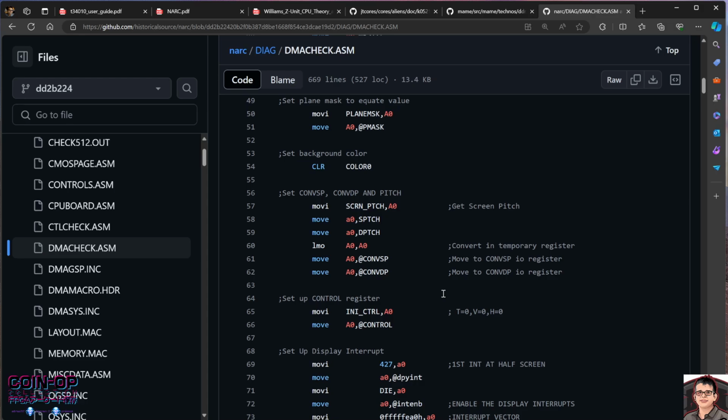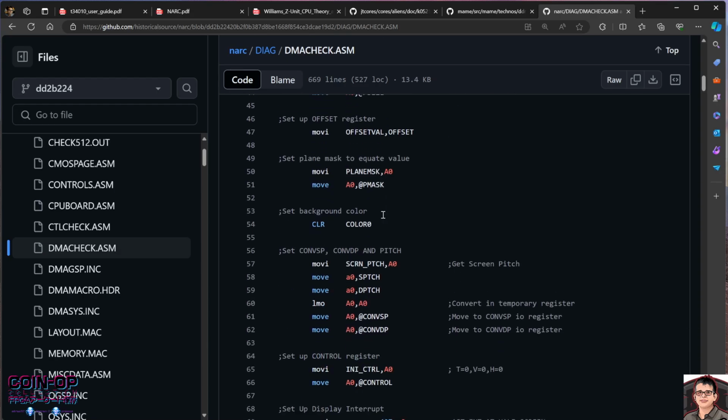I wanted to figure out what was going on, and this is where the source becomes very important. Since there are no hardware sprites, there's no RAM format, obviously. It uses its own scratch RAM to do its own thing because it's all done out of the CPU. So you want to get into the source code to tell you how the thing is actually drawing objects. There are software objects, software sprites, and software backgrounds. All that stuff is in the program ROM.